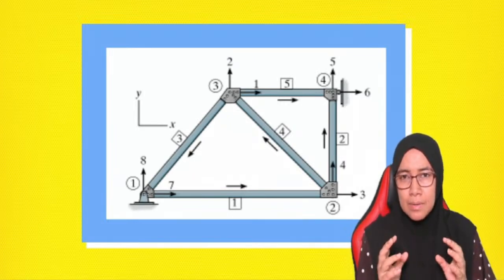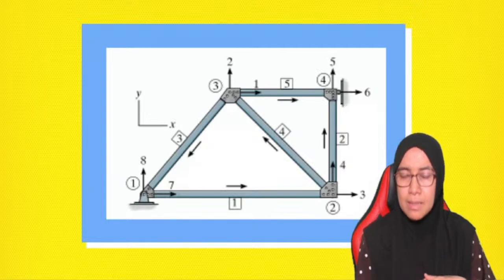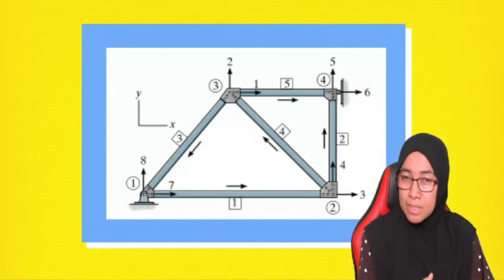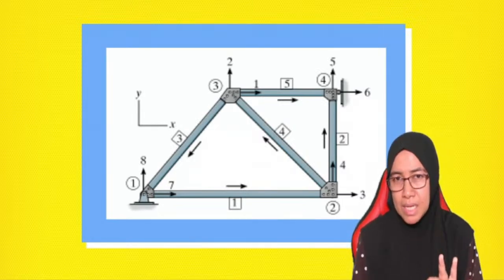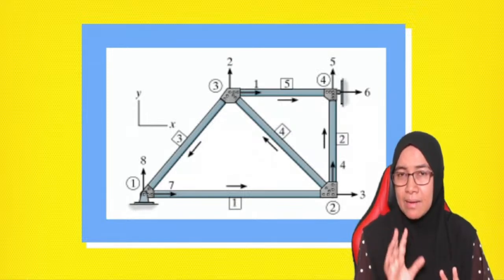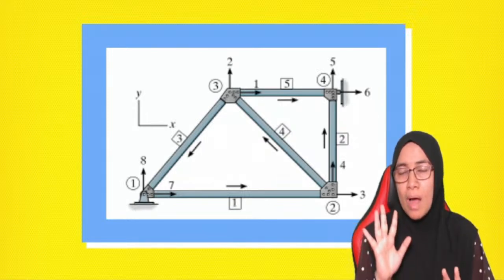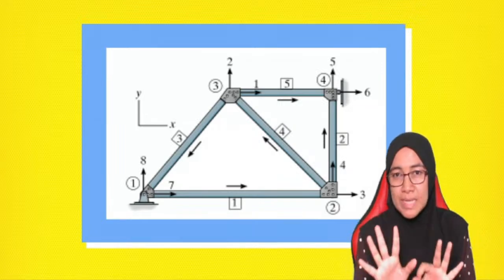Because we will have to determine unknown displacement and unknown reaction. If unknown reaction is 3, and we know that in total there are 8 degrees of freedom, it means 5 belong to unknown displacement. So total is 8.